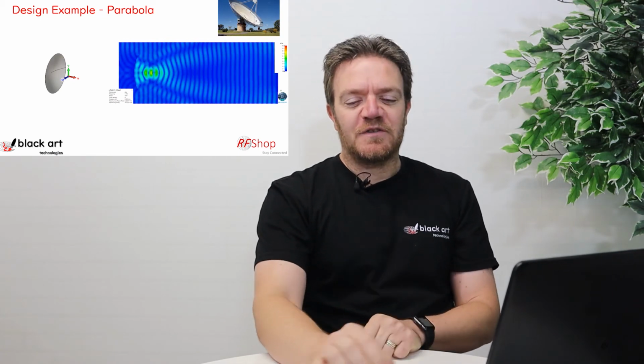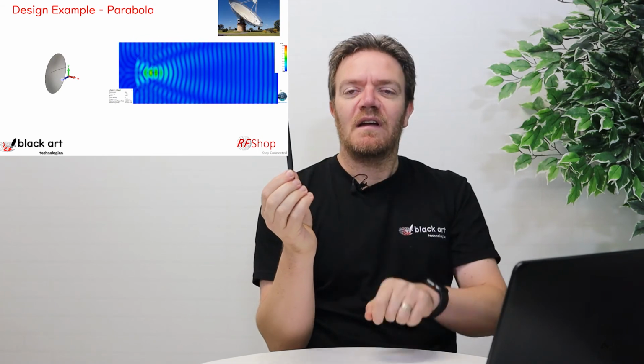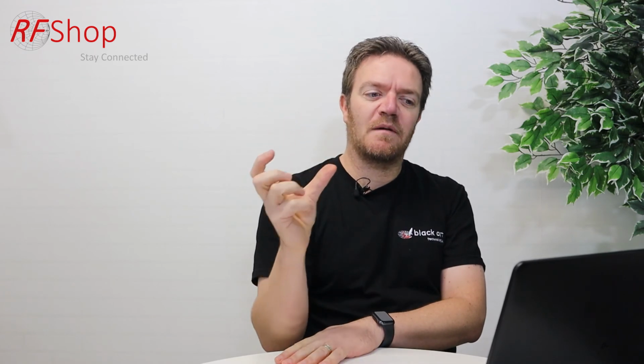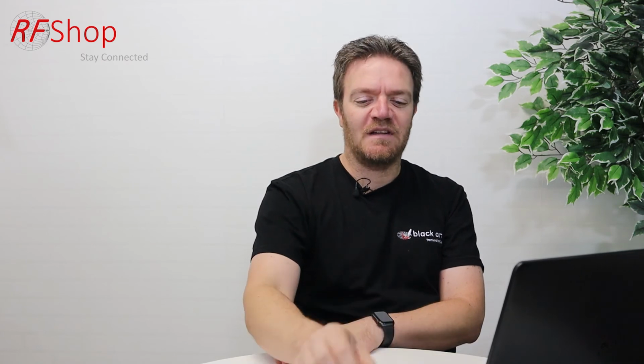Now, why I showed you this antenna, this dipole with a reflector and a director, is that it's actually a nice little feed antenna. So that antenna, as such, I am putting in the focal point of a dish, and I just want to show you what kind of end result you get. Remember that this antenna by itself was a 2 dB antenna. It's a donut. It sends everywhere. It's not a great signal going anywhere, but it's going everywhere.